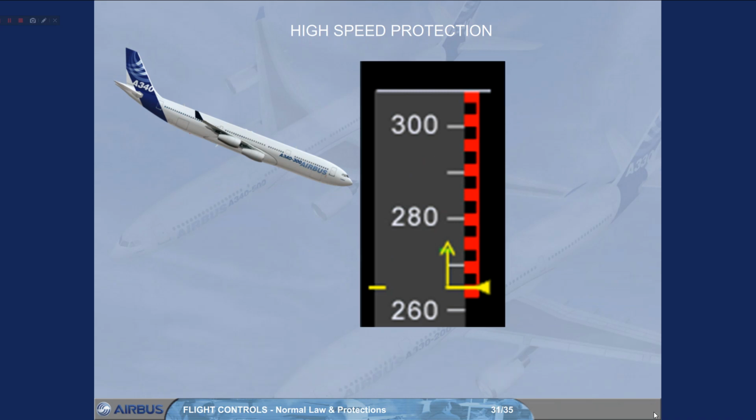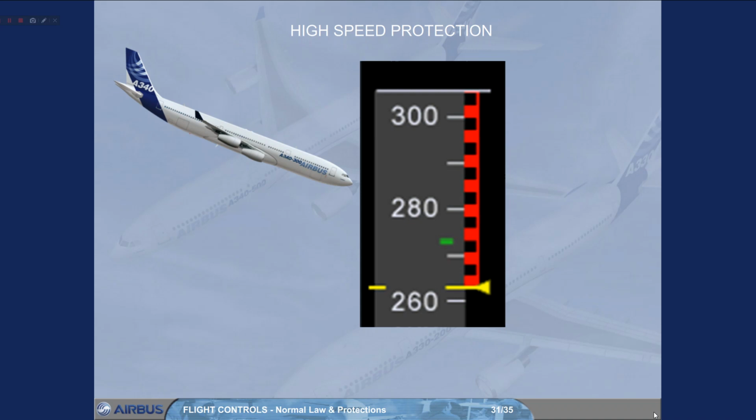If the airspeed or Mach increases to the protection activation speed, the autopilot will disengage and the flight control computers send a pitch-up command to the control surfaces to prevent further acceleration. The side stick authority is reduced, but the flight control computers will permit momentary exceeding of this speed for maneuvering if necessary. With stick released, the speed will return to VMO-MMO.